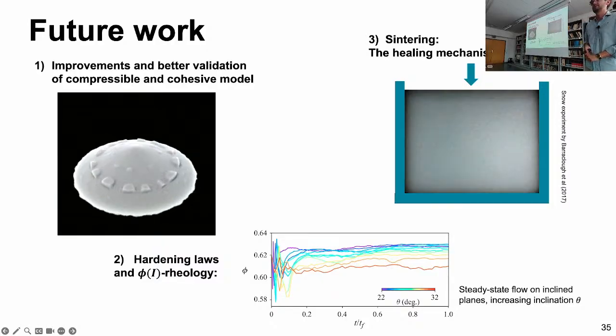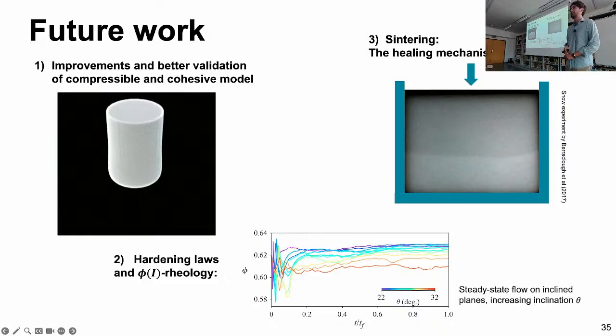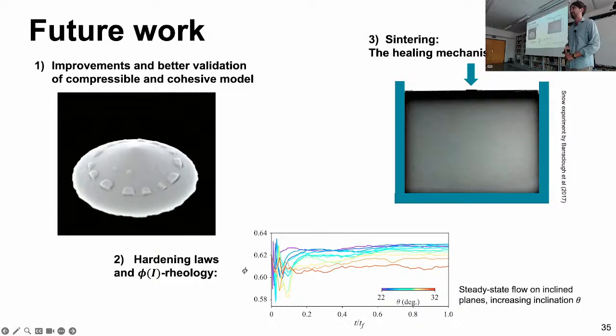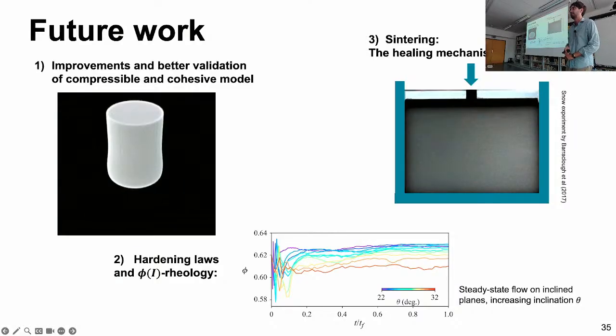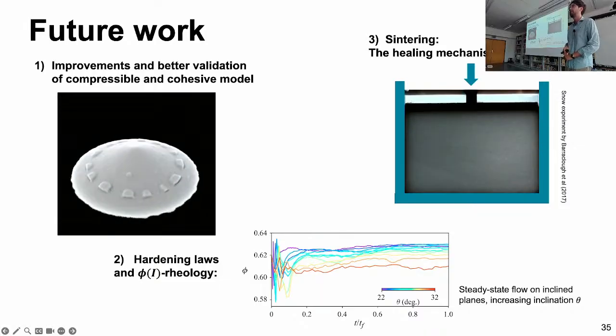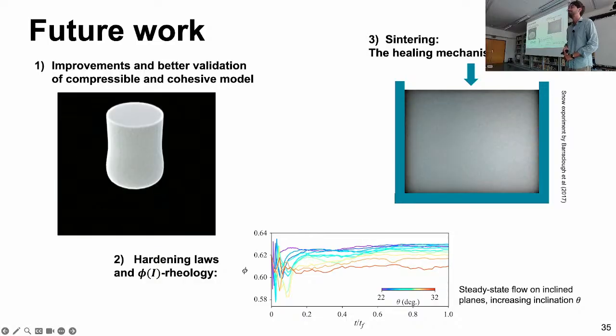A very interesting and impressive simulation. My question is about the modeling part. All the models that you consider, the Drucker-Prager model or the Cam-clay model, are only based on the first two invariants of the stress tensor. Yes.